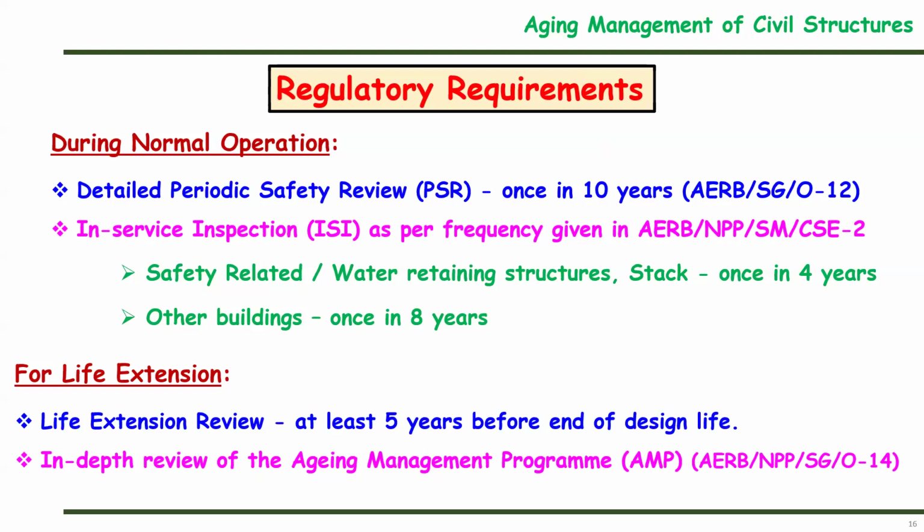Okay, and if we want to consider the structure for possible life extension, then the life extension review should be carried out at least 5 years before the end of the design life, which I have shown in the previous slide. As per some Eurocode, it is about 50 to 60 years if we follow all the codal guidelines and design the structure. We also have to carry out an in-depth review of the aging management program as per the AERB guidelines.